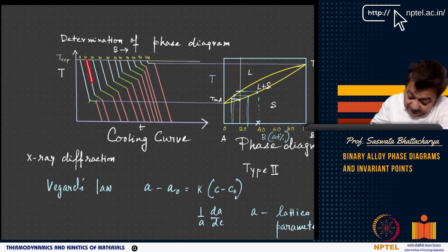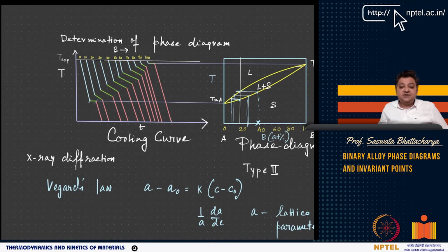Now you see, and then you have this, right? This is the cooling segment. This depends on the conductivity of the liquid. This segment depends on the conductivity of the solid, right? However, if you look at the green segment, the intermediate sloping segment, it is nothing but the segment where you have liquid plus solid coexistence. You have two-phase coexistence in this segment because of the change in slope. So this is one slope. Now there is a change in slope, and then it comes back.